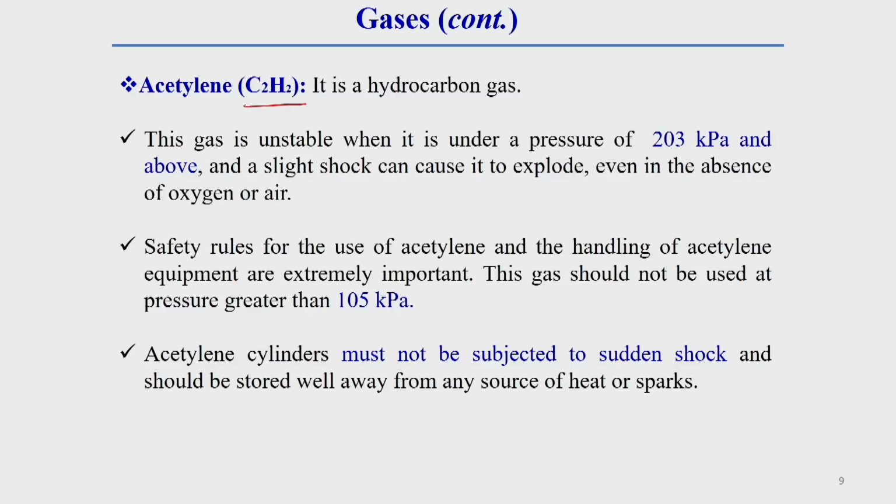This explosion can happen even in the absence of oxygen or air. So you should keep this in mind from a safety point of view. We should keep the cylinder pressure below this. The safety rules for the use of acetylene and the handling of acetylene equipment are extremely important. You should keep this in mind.